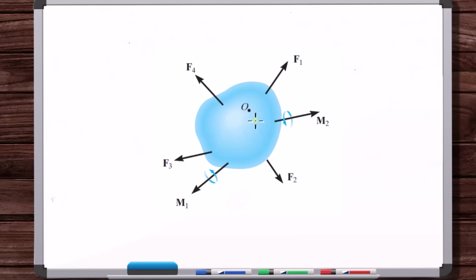As you work with the free body diagram or change the design, you're always monitoring what the net moment about that axis is. Your whole design is dependent on getting the right moment about a point. Sure. But that's not part of the free body diagram. You don't represent on a free body diagram a moment about a point as an inherent force on the system, like you do a couple moment.